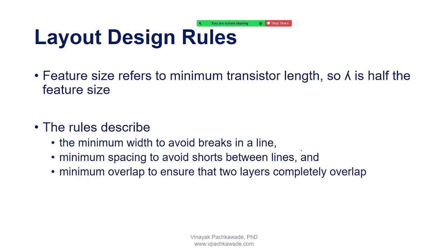So lambda, do we call it by any term? Lambda is just a design parameter when you draw the layout. You will know the feature size or the technology node. So you will not talk about feature size, you will simply say lambda is half of that feature size.